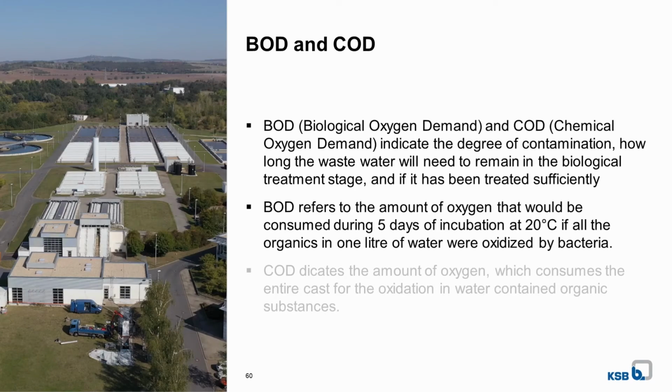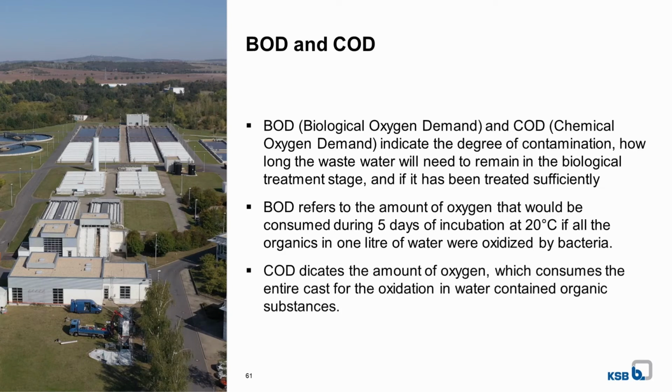The BOD refers to the amount of oxygen that would be consumed during 5 days of incubation at 20 degrees Celsius in order for the bacteria to oxidize all organic substances in a litre of water. We could also say, what do the bacteria need for their metabolic processes? The COD is used for direct chemical processes. It indicates the amount of oxygen needed to oxidize all organic substances contained in the water. An oxidizing agent decomposes the biodegradable and non-biodegradable substances and produces carbon dioxide. The COD is mainly used in the context of industrial wastewater treatment plants.